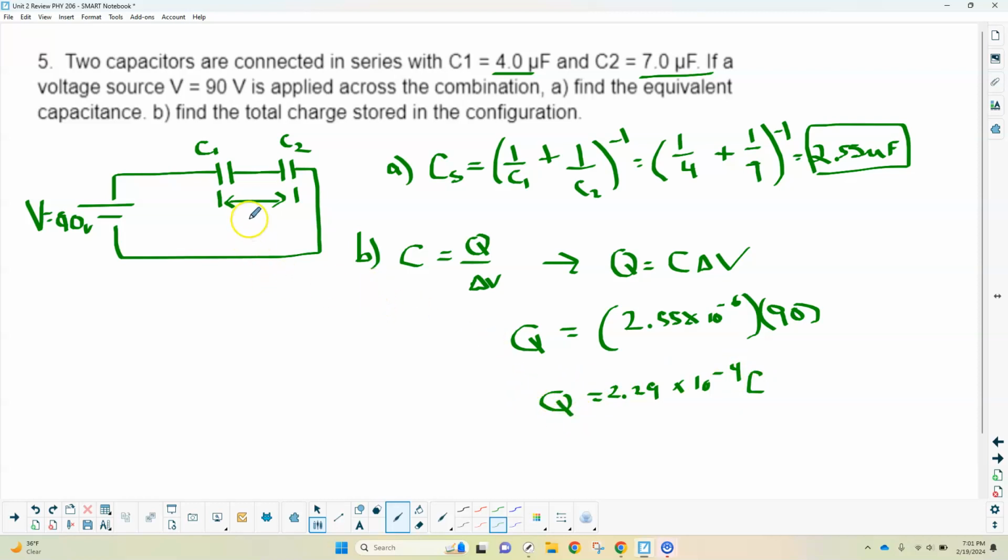That's capacitors in series. Again, the total capacitance goes down because you're increasing the distance. So if you think about it in terms of this equation, epsilon naught A over D, the separation is increasing, so the capacitance drops. The voltage is held the same, so again, the charge has to drop to match or mirror the capacitance.